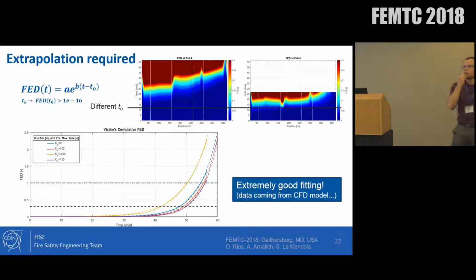Unfortunately enough, if you have been using FDS in tunnels, there is some point where your fire gets ventilation limited, and you have pressure issues, and then the simulation gets unstable, and after some time it's highly probable that your simulation will crash due to numerical instabilities. And that's actually what happened, and if you try to simulate 1 hour, it's highly probable that will happen. Even though this happened to some of the fires, we had already one run that went out to 55 minutes.